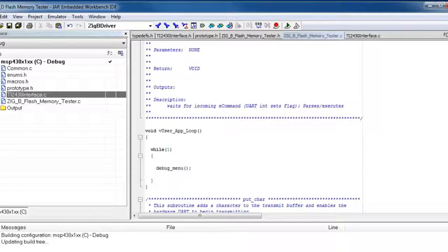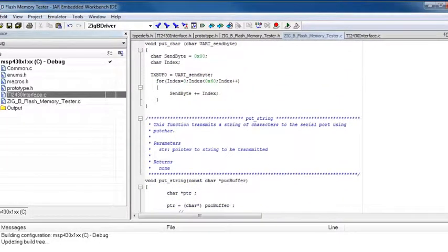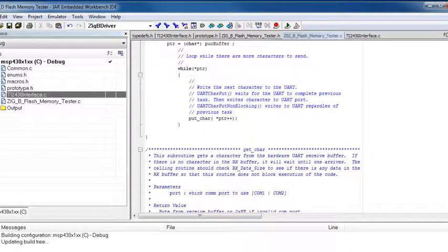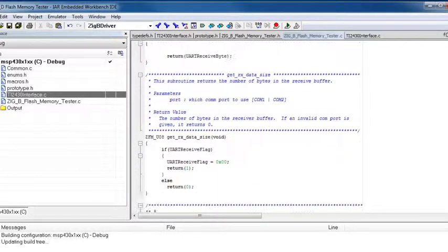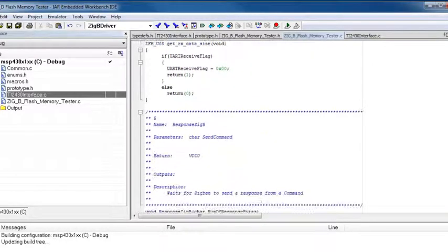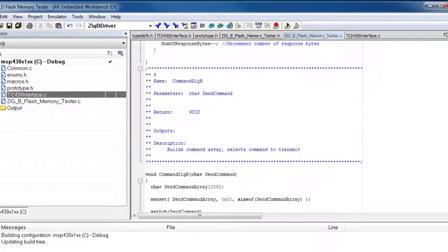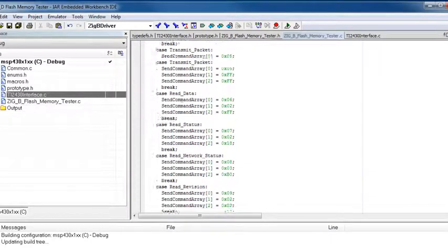And this is where the magic happens. It is where the smart core of the microcontroller code is. This function provides a user console in which to send commands and receive responses from HyperSerialPort. Using the debug menu, we can monitor all of the interaction to and from the Zigbee emulator. For the microcontroller to communicate with the built-in serial port, I'll add several functions that will handle writing the characters and strings out of the serial port.